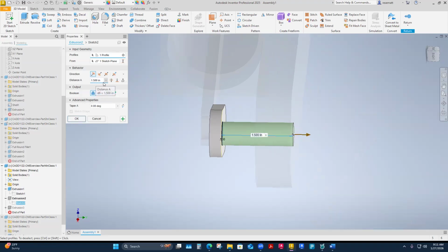And I'm like, oh, that wasn't quite right. Actually, I want it to be that plus 0.25. That's actually a legit dimension too. I have what I need plus a little bit added for something. Sometimes this is the way I add tolerances into my part. I might have the basic size as my dimension, and then I might enter a tolerance in here. And then when I go into this dimension, I can see, oh, there's my tolerance I've applied here. So I do that strategically.